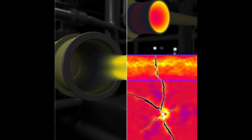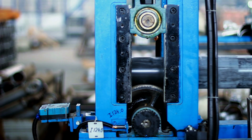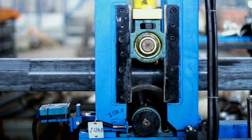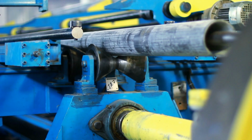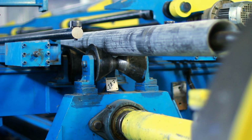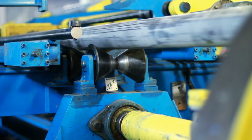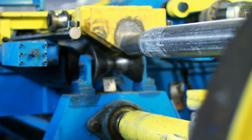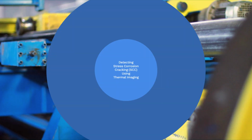In contrast, internal localized stress from features like notches or threads usually results in specific, concentrated temperature differences around those points only. By analyzing these thermal patterns in detail, we can identify whether the heat signature is from a widespread load affecting the entire structure or a localized stress concentration caused by design features. With experience and the right techniques, thermal imaging allows us to accurately pinpoint these areas, making it an essential tool for proactive maintenance and component analysis.